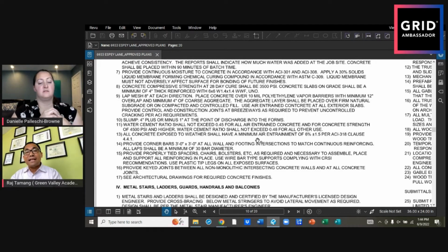So what happens now is, I have concrete outside, and it's raining, water goes inside the concrete, and now it's frozen. The water becomes ice, and ice volume is 10% more, so it starts putting pressure around it.